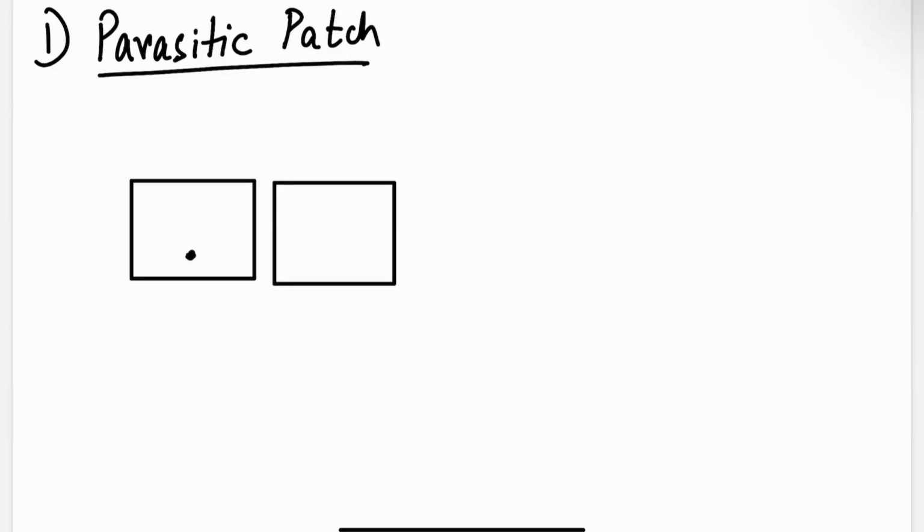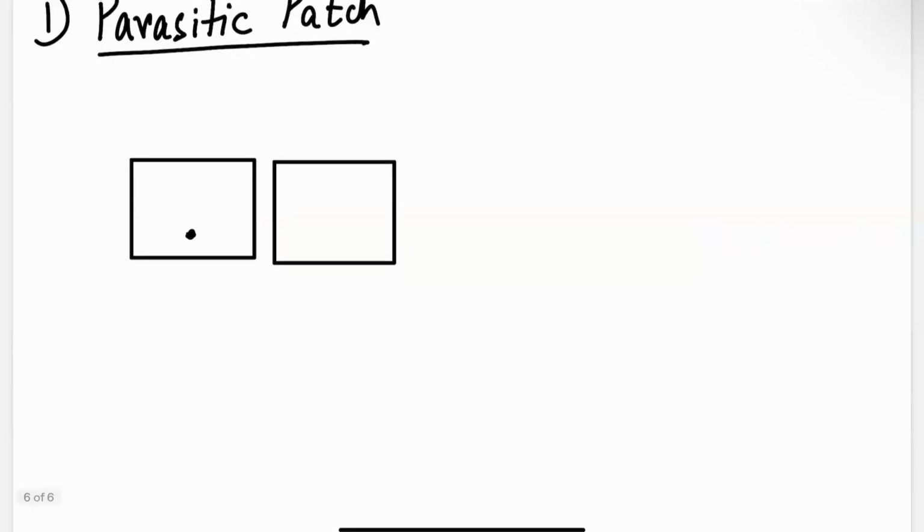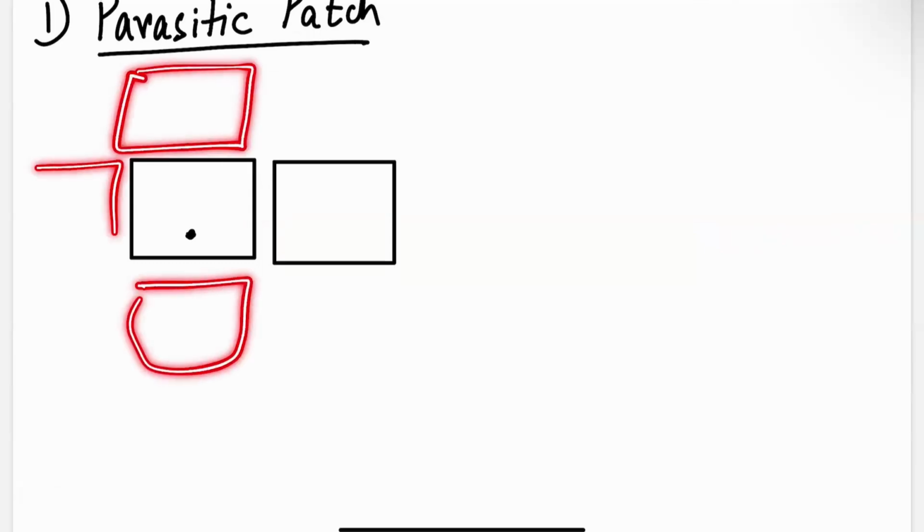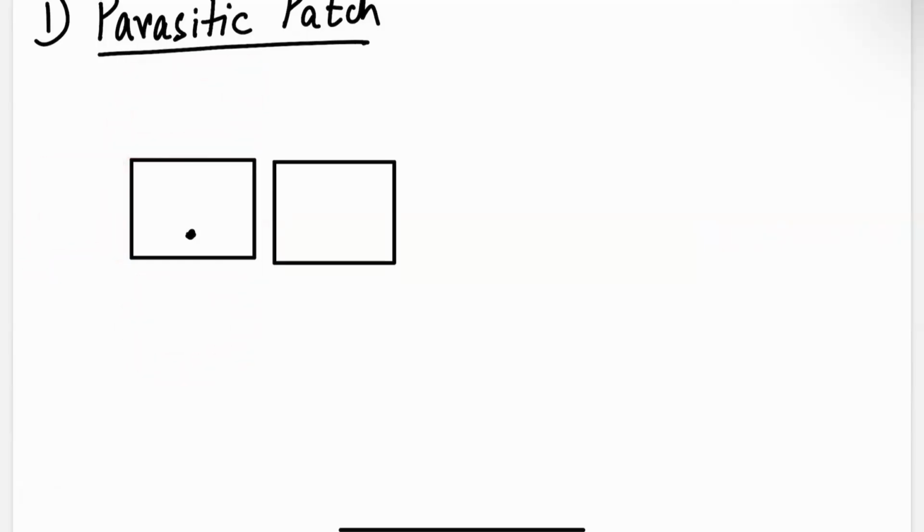There is some coupling between these two from the fringing fields. So when you excite this, this also gets excited because of the fringing fields, and because of their same size you get some coupling between them. So it's like two coupled resonators where one of them is driven, and that can enhance your bandwidth. Of course, you can extend this and put another patch out here, a patch here, a patch here, and you can get many resonances. Not always easy to control, but you can get pretty large bandwidth.